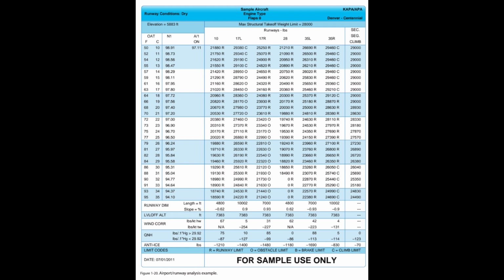A Part 25 transport category and Part 23 commuter category aircraft's OEI takeoff flight path is established by or on behalf of the operator for a particular aircraft type, and then limit weights are determined that assure clearance of any obstacles under that flight path or within the prescribed lateral distance from the flight path centerline. It may be necessary for pilots and operators of these categories of aircraft to use the services of an aircraft performance engineer or airport/runway analysis service provider as a means of compliance with the requirements of Part 121 Subpart I or Part 135 Subpart I concerning OEI-net takeoff flight obstacle clearance and takeoff field length requirements.